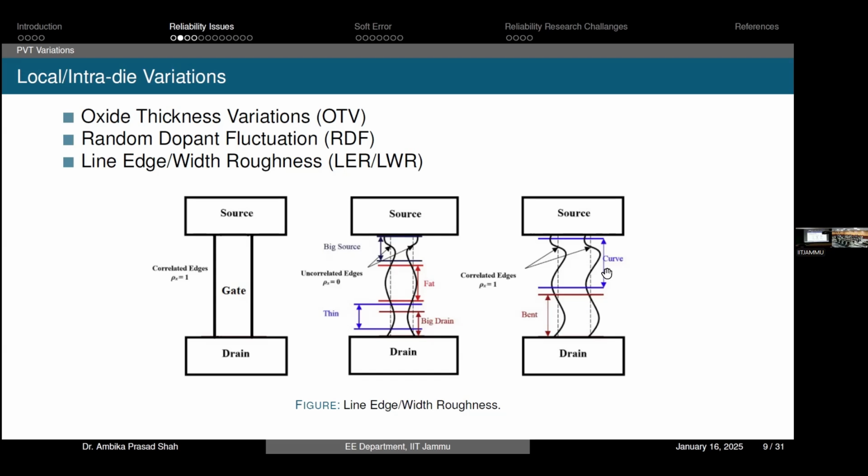If you are fabricating older technologies, like large, long channel devices, then the same wavelength of light might be used and you can properly get the devices. But at the newer technologies, you cannot get the same pattern you were expecting, because of the difference between the wavelength of light and the technology node you want to fabricate.